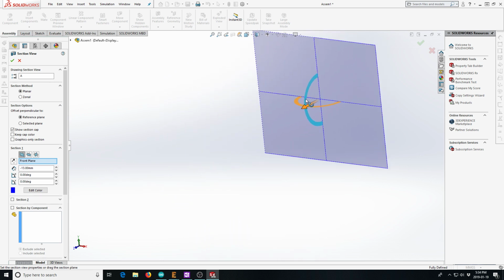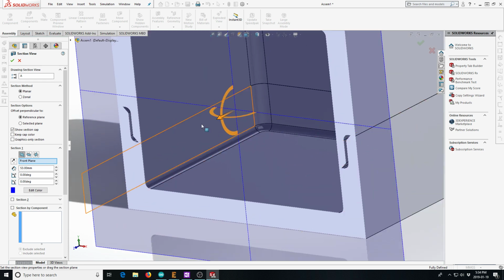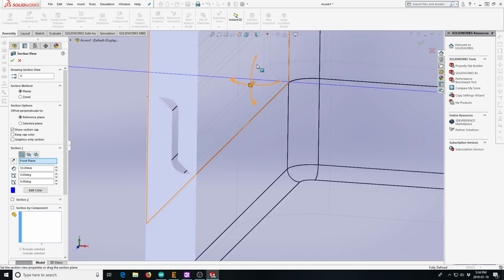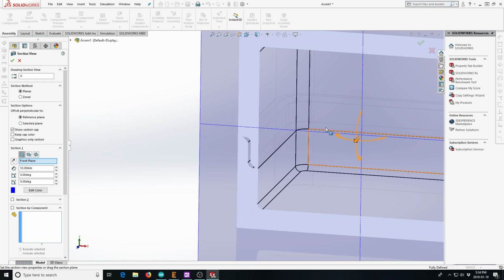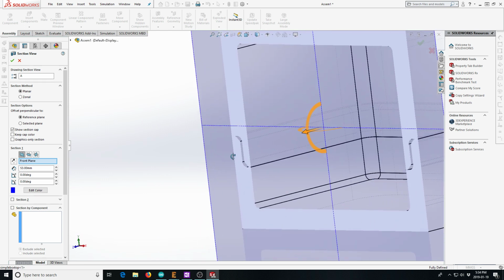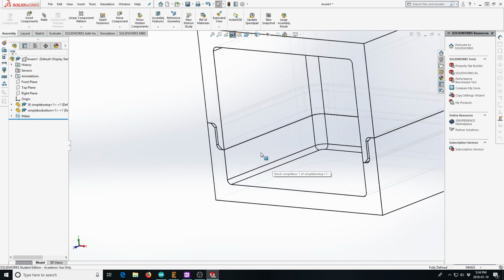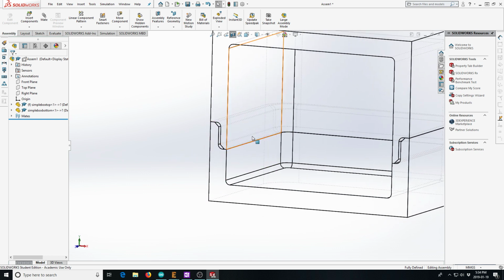So it was off in space someplace, and I have to drag it to where I want it to be. And so you can see from the section tool that I'm looking through a cutaway, and from this, if I choose hidden lines, you can see that there is this spacing here, gap, between the two parts assembled. And that's good, because that way they'll actually fit together. There. And you can play around with that to whatever spacing you like.